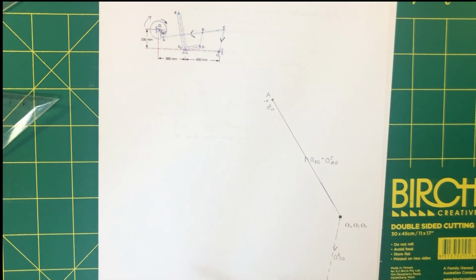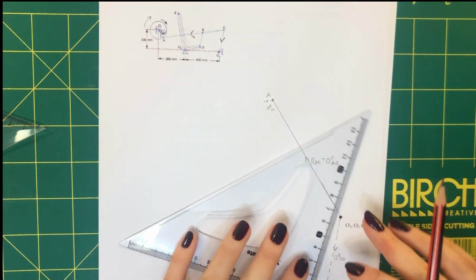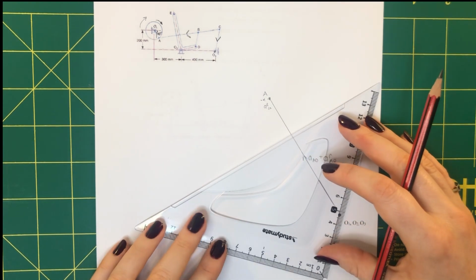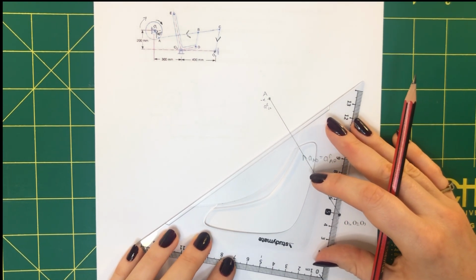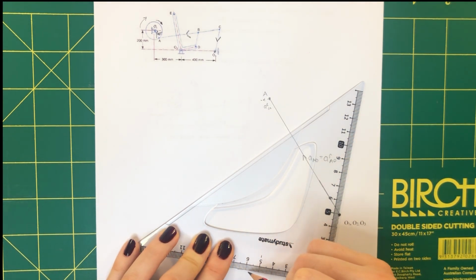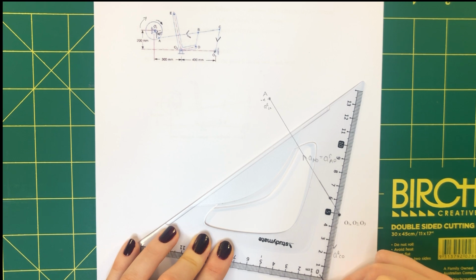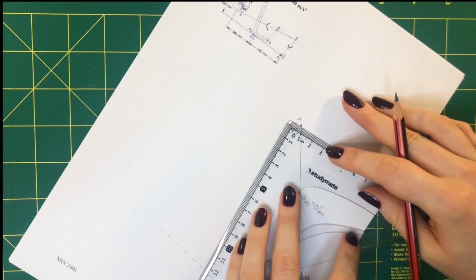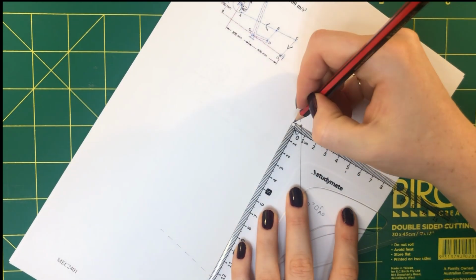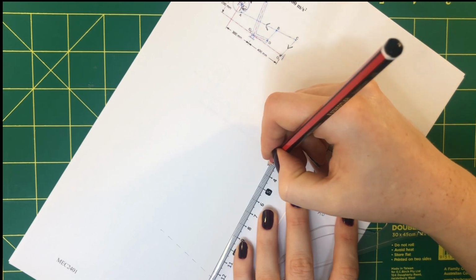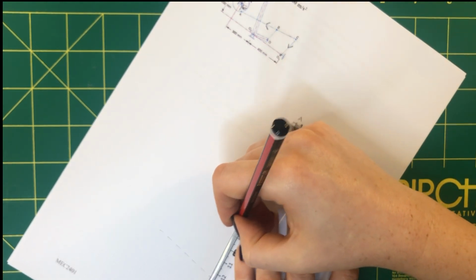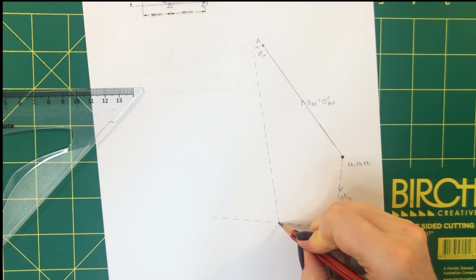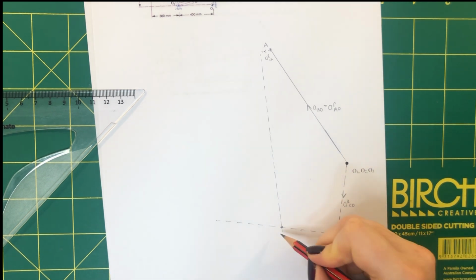Now I'm going to draw in my tangential lines, remembering that they are perpendicular to the radial acceleration or perpendicular to the link. I don't know the length or the direction, I just know the location. So this line could extend down there. And then we have this line, the tangential component of CA, perpendicular to the link CA or the radial acceleration. And where these two cross, this is point C.